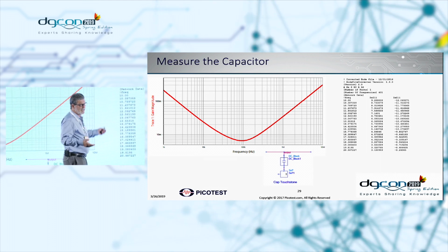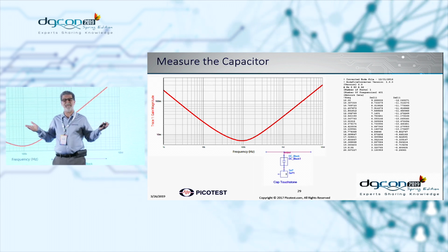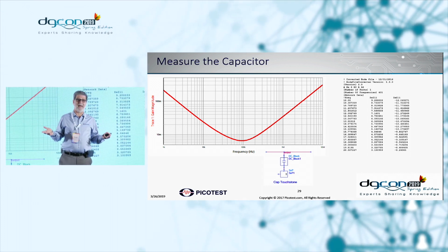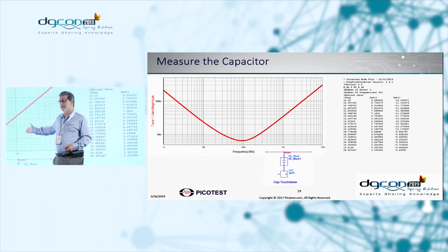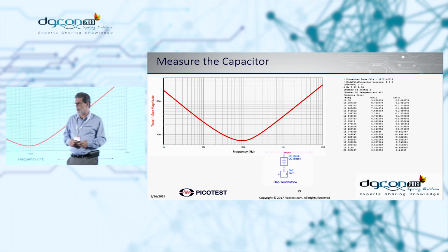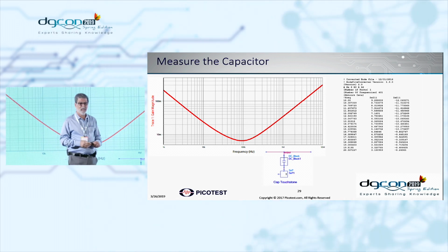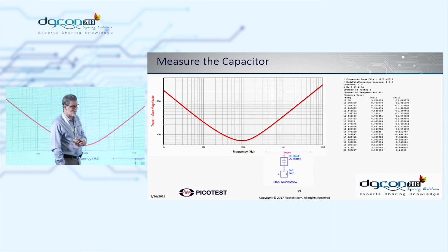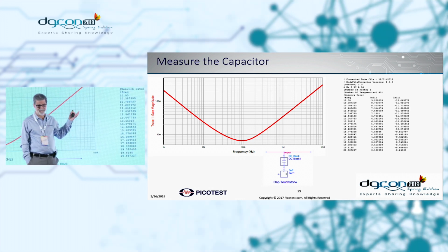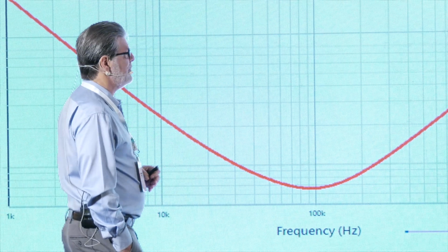For example, for a given excess inductance, if I know I need a 100 microfarad cap or a 220 microfarad cap, I can go through the catalogs. Maybe you've got your favorite vendor. I happen to like the red ones from Würth. They make really good caps. But when I go look for caps, they don't have so many 100 microfarad, 10 or 20 milliohm ESR caps. So I've got to find one that's close to what I want. I won't get exactly the capacitance I want. I won't get exactly the ESR I want. And I probably won't even get exactly the ESL I want. I'm going to find the best capacitor that Würth can offer. Once I choose that capacitor, I have to tune all of the power supply parameters to match that. That's the trick. And so it's actually backwards. We actually select the capacitor first, and then we design a power supply around it.